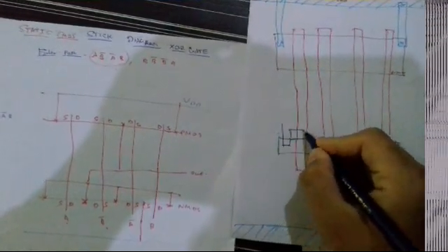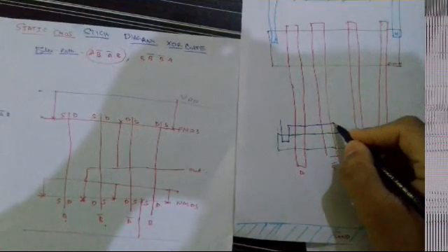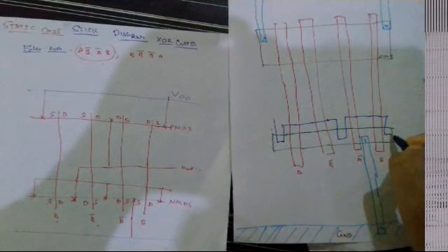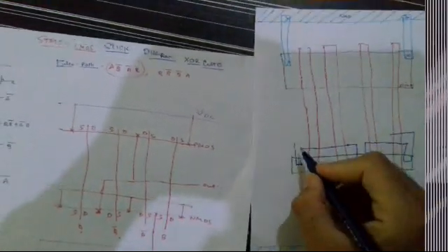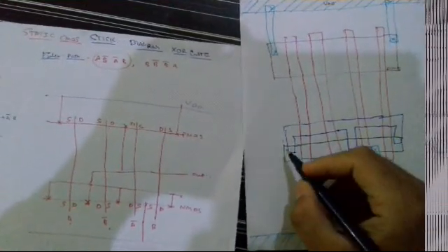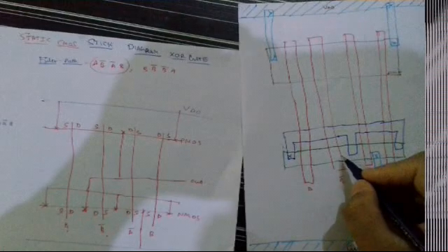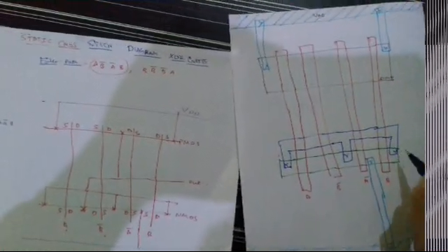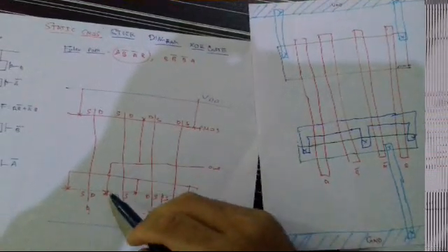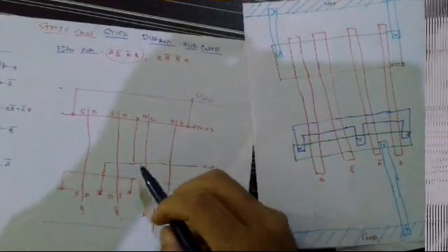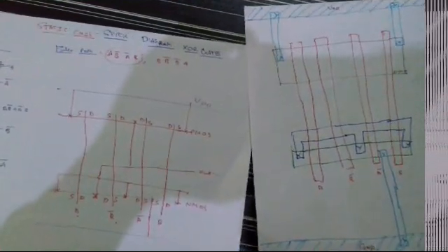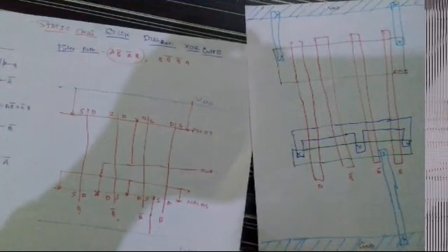This one, and this one, and the last one. The metal 2 width is greater than the metal 1 width, which can be seen in the video of the rules which I will provide in the description. Now the last thing left is to make a connection for the output. So take one wire from here and one wire from here and make the connection for the output. I will again use the metal 1 layer which is of blue color.